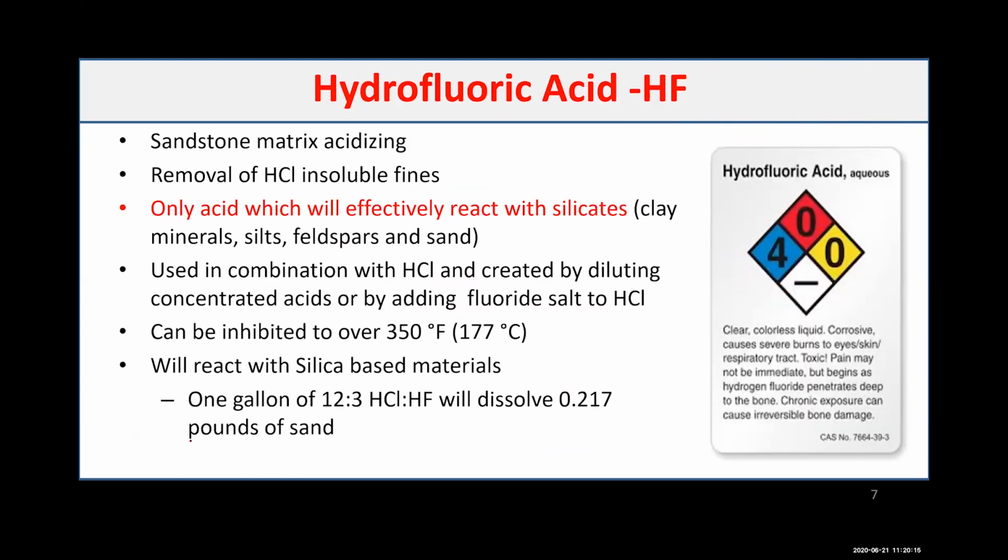The second part is the hydrofluoric acid, or HF. Again, this is the only acid system that can actually dissolve silica or silicate. In general, it can dissolve clay, can dissolve silt, can dissolve feldspar, and definitely can dissolve sand. That's why when you hear HF, it should come to your mind: it is a sandstone treatment. We do not use HF except for sandstone.